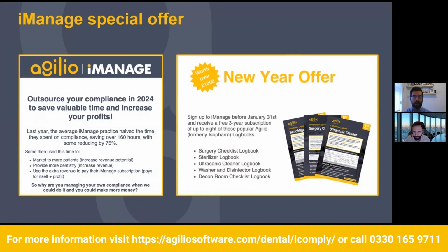Scan through it. Look back at that last 12 months. Has anything changed in the practice? Ask yourself questions. Is it all still relevant? Is it still applicable? And simple things as well, especially from a Legionella point of view. I've seen this a lot when I've been out visiting practices, but I've seen a historic assessment that was done in like 2020. And that assessment says that the practice had a cold water tank. Yet now they've got a combination boiler, because in 2021 they took out that cold water tank and replaced it with a better hot water service. So again, that assessment is no longer valid, and that hasn't been picked up on. So check them often and keep them relevant.